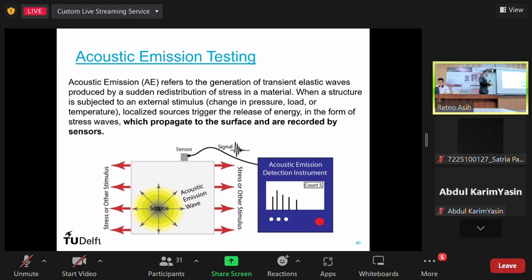You have a crack or a source of mechanical wave, which is sound, and you have a sensor, and the wave propagates through the material, and you can hear it. And once you hear it, it's similar to this detector that monitors your heartbeat, that they put and they listen to the heartbeat and they say, okay, if you are okay or not. It's quite similar concept. But we are listening to the sounds of the cracks. So the crack has to be active in order to generate. So it means that it can only detect the active cracks, not the passive.